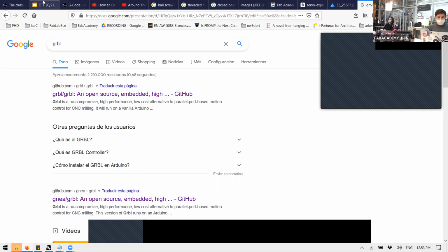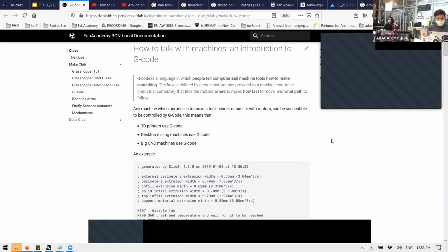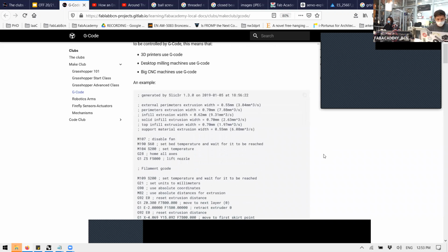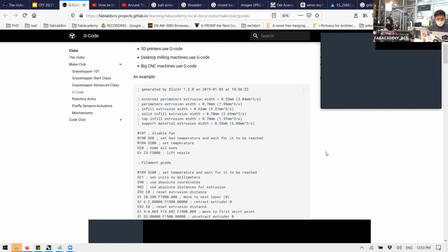G-code interpreters read G-code. That is basically the standard for sending commands for any fabrication equipment: 3D printers, laser cutters, CNCs. As you know, some machines use their custom G-code style. For example, Roland has developed their own custom G-code, so they only read their own proprietary type of file, just because they want to enable some special characteristic that is not enabled by default by other interpreters.